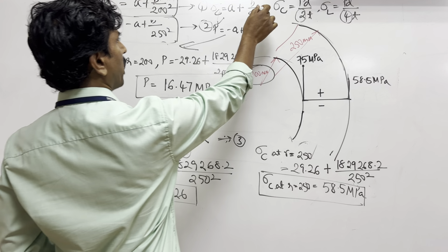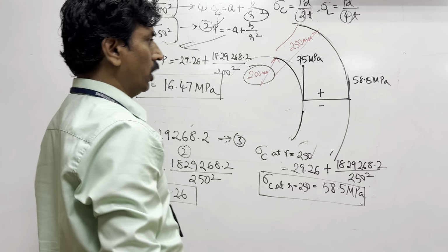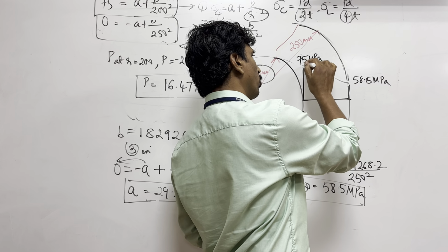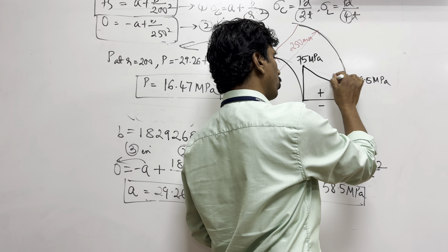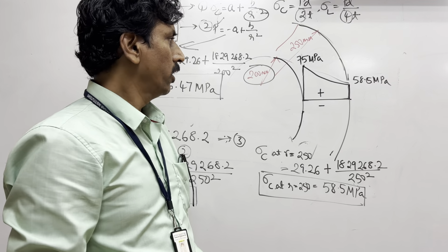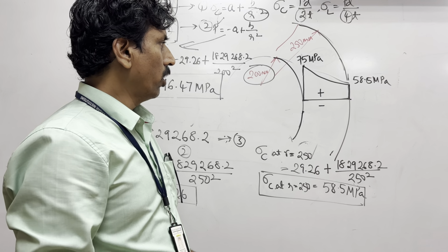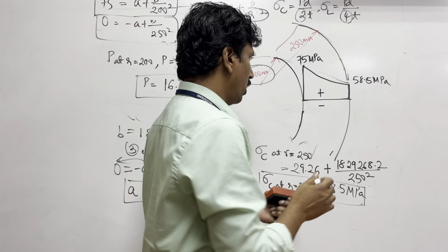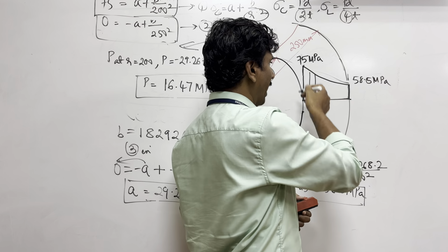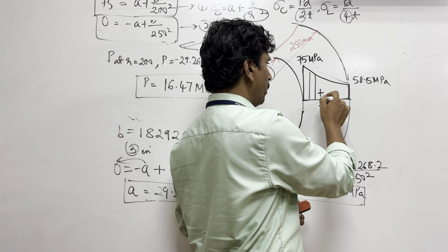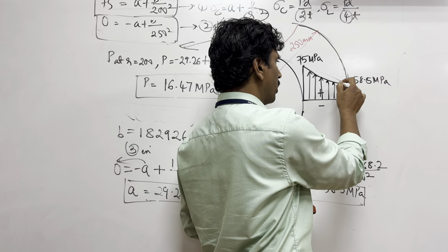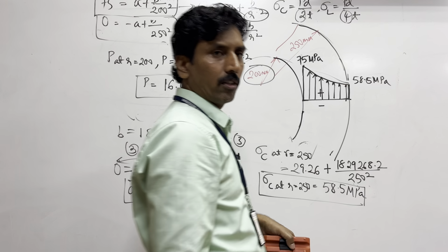Now the variation is actually parabolic because you have got this r square term here. So therefore it will not be a linear line, and you can't join these with a straight line. You have to draw a curve to show that the variation is parabolic, something like this. Instead of hatching, people show the tensile stress applied on the material like this.